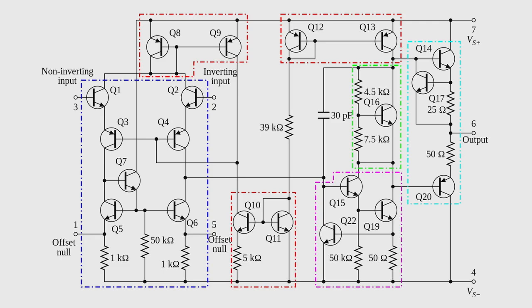It provides a high differential amplification gain with rejection of common mode signals, low noise, and high input impedance. And that drives number 2, which is a voltage amplifier that's outlined in magenta. That provides high voltage gain and a single pole frequency roll-off. That drives number 3, which is an output amplifier, outlined in cyan and in green.